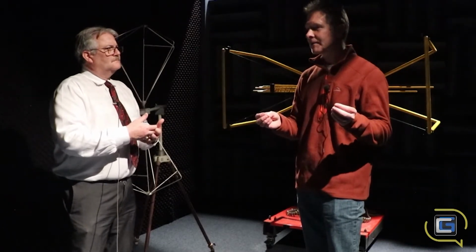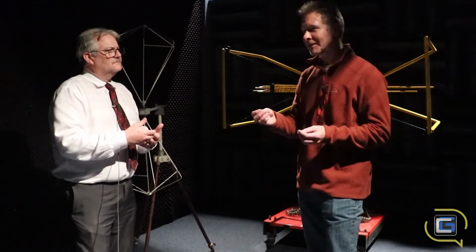The main switching frequency on the front end of a power supply is typically in the range of 60 to 70 kilohertz. Well, you can see for FCC, if you don't care about 150 kilohertz or below, that 60, 70 kilohertz is out of the range, but it's right in the middle of our lower end.